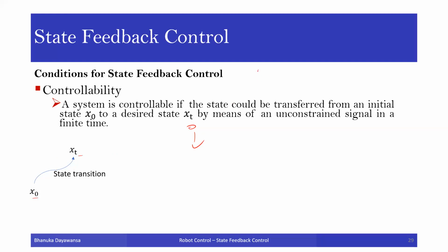So if you have a system dynamic equation, X dot is equal to AX plus B ut. Now this state variable is controllable, because by changing ut, you can control it. But if the ut was not there, it's not controllable. It's all homogeneous. Whatever the system parameters are will decide how the state is going to be after a certain time. It's not controllable.